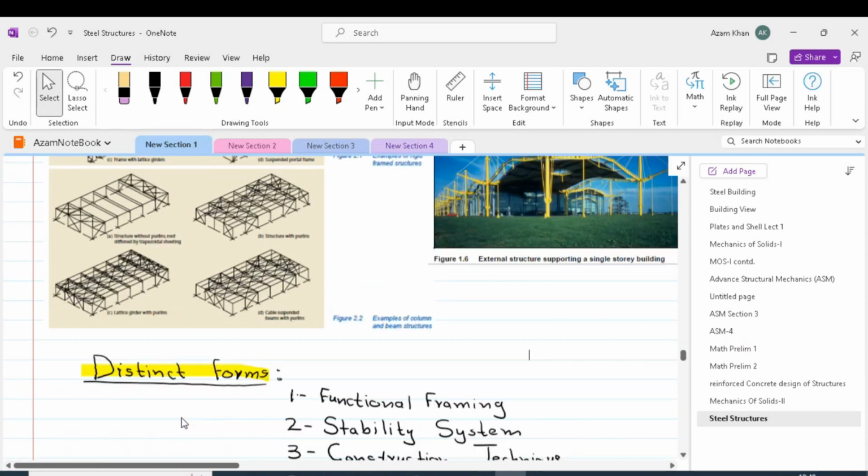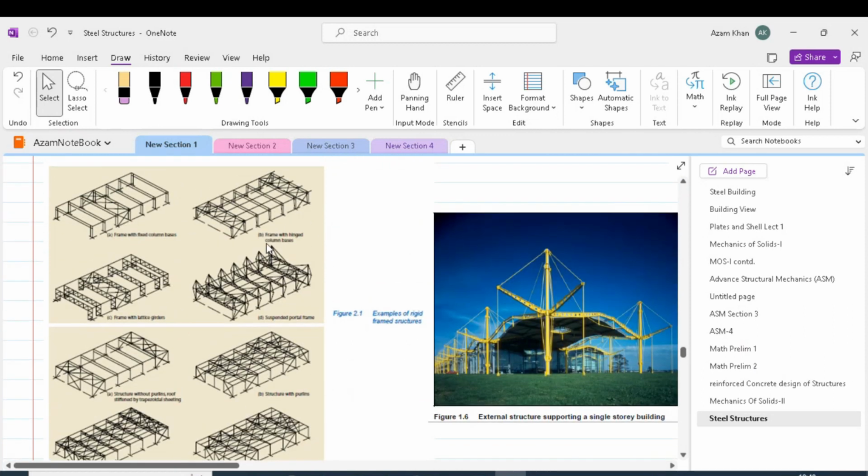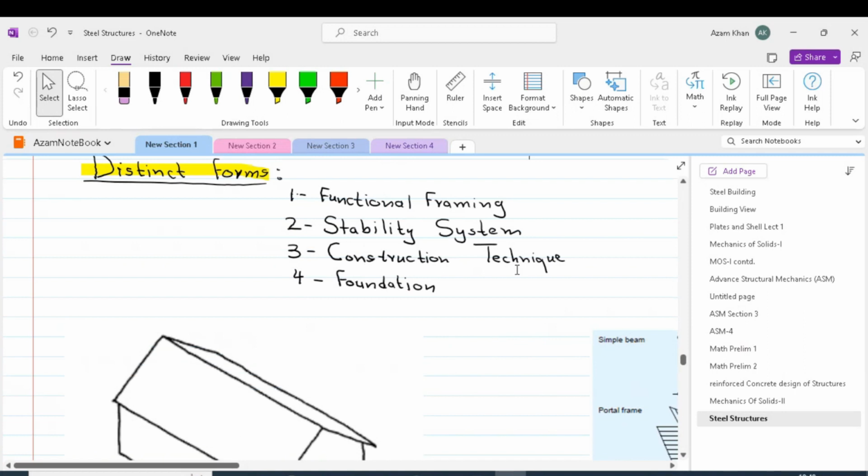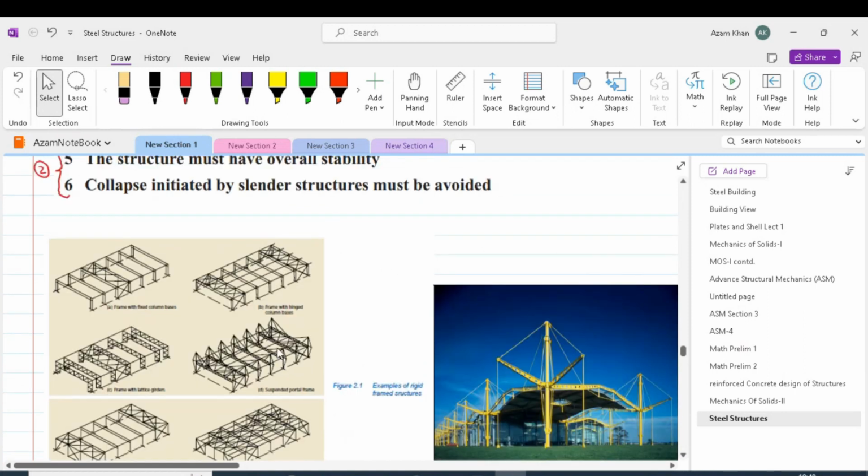We can distinguish the construction technique of all these systems. We can also distinguish all these structure forms in terms of construction techniques. For example, the construction of a normally single story, single space steel structure involves first of all construction of a braced bay, and using that braced bay as a stable box, one can stack a series of other bays behind and in front of it.